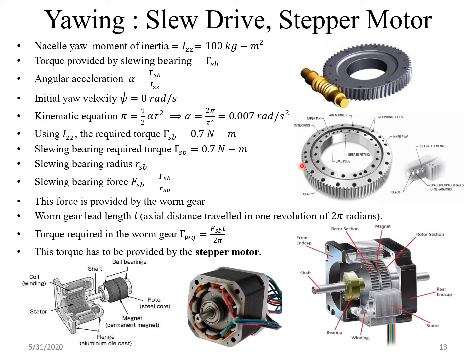The rotation of the entire nacelle about the tower axis is known as yawing of the nacelle. Active yaw control system consists of a slewing bearing drive with a mated worm gear between the bed plate and the base plate, a stepper motor to power the slew drive, a microcontroller to actuate the stepper motor, and an anemometer. Whenever the anemometer senses a wind direction change, it signals the microcontroller, directing it how much to turn the slew drive, such that the nacelle is aligned to the new wind direction. The slew drive has to be capable of both anti-clockwise and clockwise rotation.